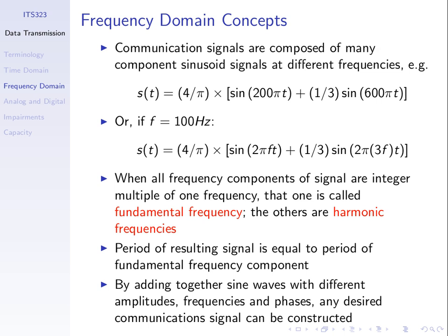And let's write it over here so you will not forget it. The general equation for our sinusoid, S of t, is peak amplitude sine 2 pi ft plus the phase phi. So of our two components, we know the peak amplitude. Of component 1, it's 4 on pi, and component 2, it's 4 on pi divided by 3. So it's just the multiplier at the front of the sine. We know the phase is 0 in these two cases. There's no plus component here.